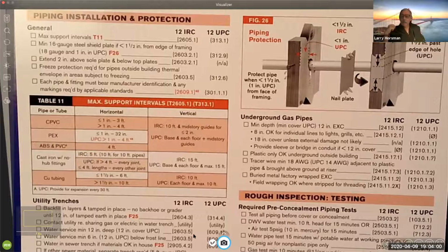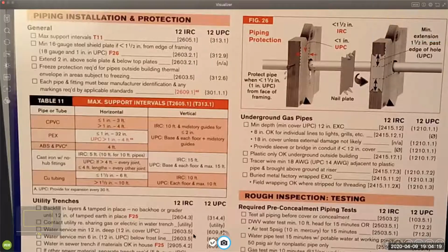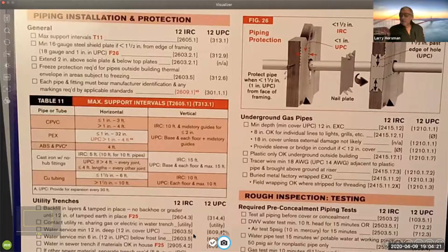That's where, particularly if you have high water pressure and a short throw valve, when you shut the water off quickly, it'll cause a pressure wave to travel back and forth through the pipes. It'll make things rattle, and in some cases cause a failure in the pipe system.